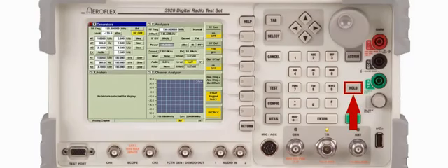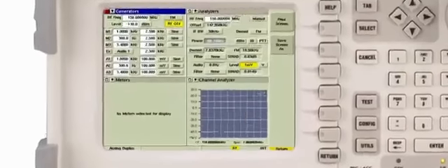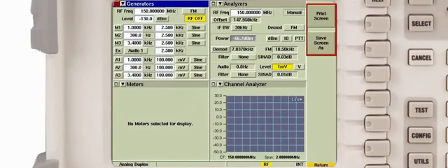Pressing the Hold key will freeze the entire display in its current state. When the screen is held, two soft keys appear that allow the screen to be printed or saved internally as an image file. Pressing the Print Screen soft key will send the screen image to a printer according to the print configuration. Pressing the Save Screen As soft key will present a menu that allows the screen image to be named and saved internally as either a JPEG, PNG, or BMP file.